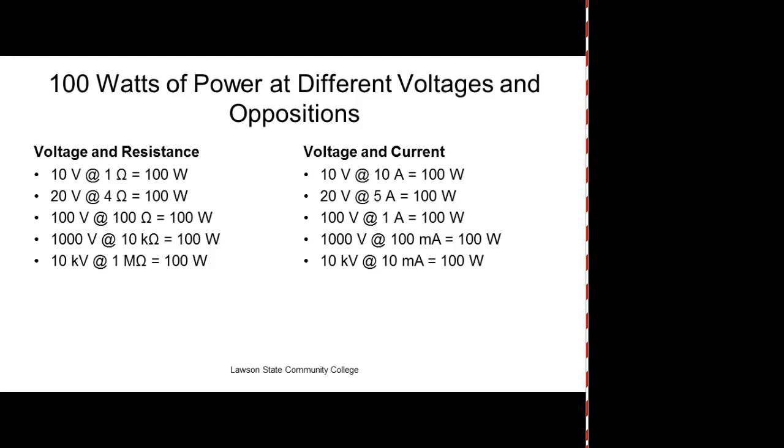If you put something designed around 240 on 120, it's not going to work at all. Okay, y'all understand that? So loads are designed to work around a certain voltage. That means your HVAC system and your electric stove and your electric water heater are designed for 240.